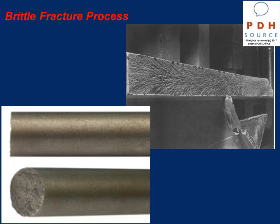There is here relatively little plastic deformation, or maybe no plastic deformation at all. The direction of the crack motion is basically perpendicular to the direction of the applied tensile stress. If this is the direction of the applied tensile stress, this is the direction of fracture, perpendicular to it.